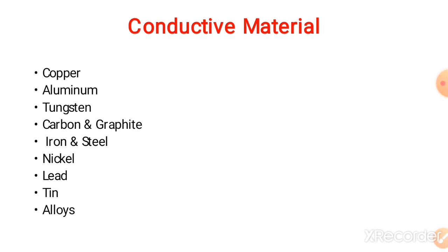Next material is lead. The lead has two important applications in electrical engineering. It is used to form cable sheath, and the second application is plates of lead acid battery. The lead sheets are required to protect the insulation of cable from the effect of moisture. Next material is tin. The important electrical use of tin is in manufacturing of low current fuses.